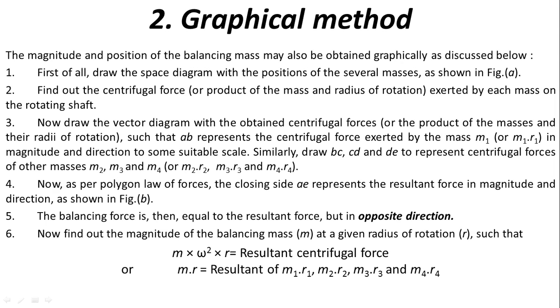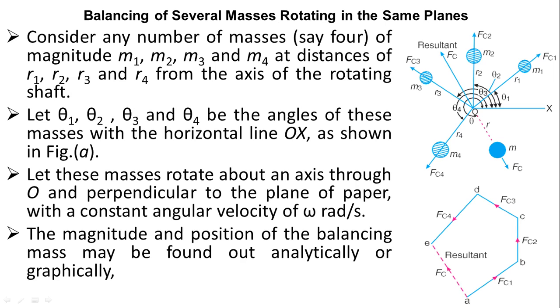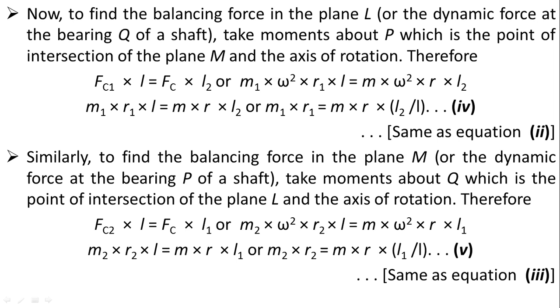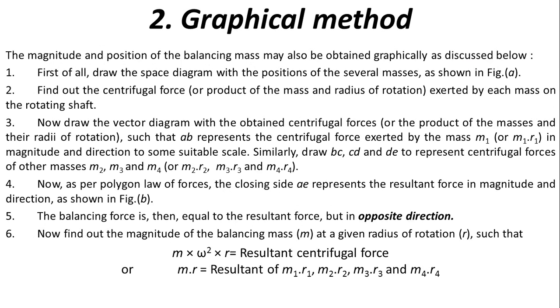Okay, because why you have not taken omega? Because omega is same. Okay, because omega, you can see here, it is having the same omega radians per second. The angular velocity will be same. So no need to again take for all the condition, because omega will get cancelled. Last conditions you have seen where omega would get cancelled. For other conditions you had seen. So like this, when it was done for the other cases, all this omega was cancelled. So same way here also, will not consider omega, so we will take only m into r.